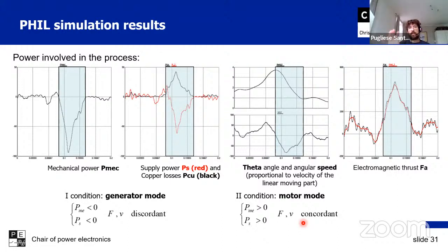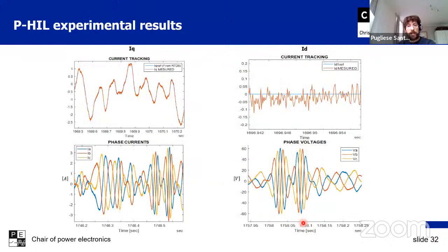But if you choose the right coefficients, sky and ground, this force will never be so high as to be in motor mode. You tune in order to always be in generator mode, and meanwhile have a good compromise of comfort and road holding.